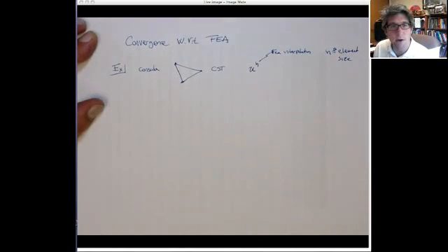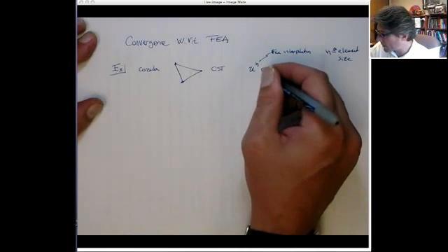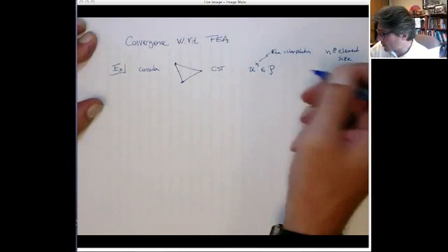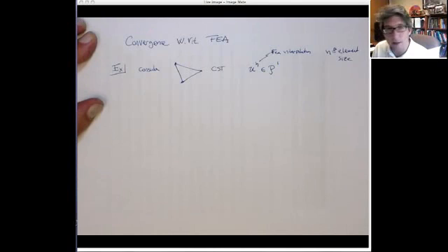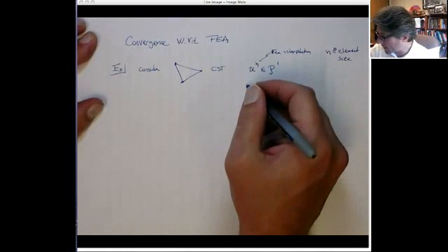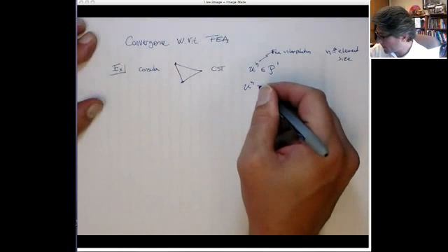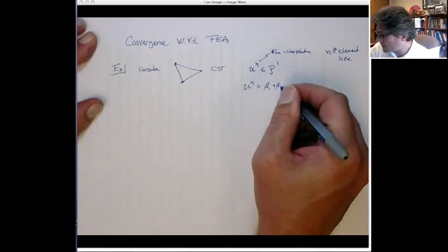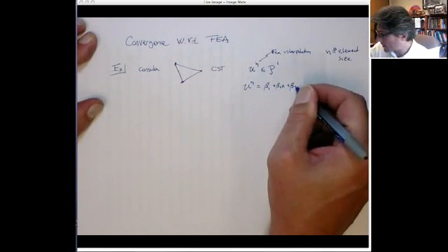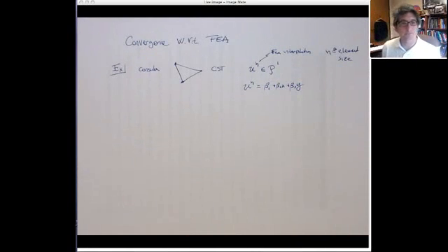So h refers to the size of the element. As h gets smaller, your error should get smaller, all right? So for a constant strain triangle, this is going to be contained in the space of linear polynomials. So that means it's something like beta 1 plus beta 2 x plus beta 3 y. That's our interpolation.